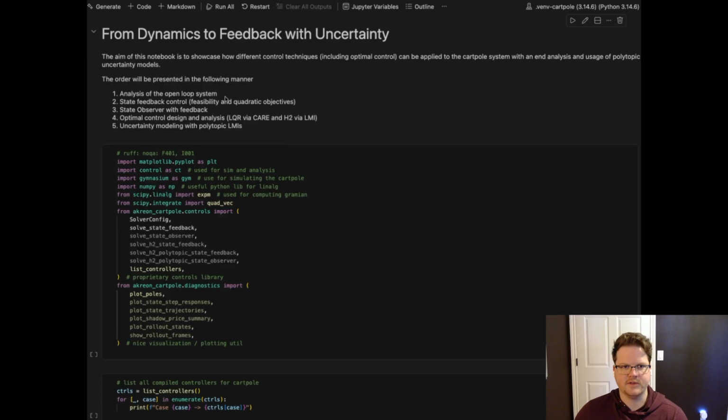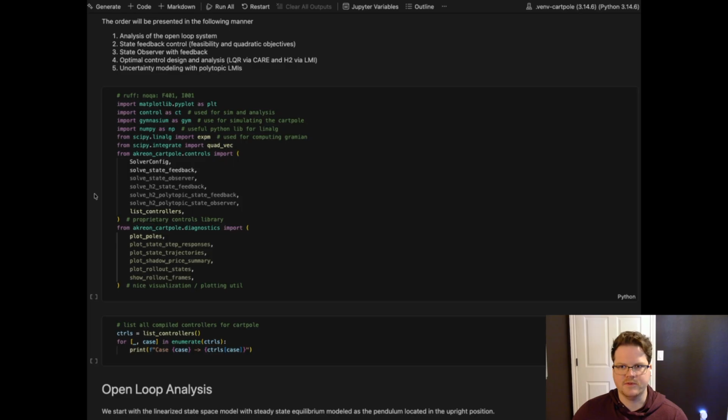I'm actually only going to use the feasibility here, though linear objectives and quadratic objectives are valid. Feasibility just shows you how the synthesis will actually carry out. Just note that the objective function is just going to be 0, so it's not per se minimizing anything. The solver that I've set up is only going to abide by the constraints that are imposed by the linear matrix inequalities, and I think it's just that for the state feedback control. All right, so let's move on.